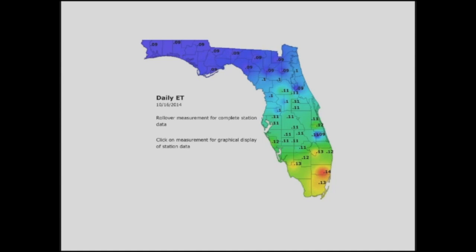All right? So that means they want to return the amount of evapotranspiration loss, right? But we know that that can change based on where you are in the state. It's very variable. In the state of Texas, you could be recommended to water a ½ inch a week up to 2 inches a week, depending on where you are, right? So it's very, very variable. In a perfect world, we'd all have a smart controller that calculated the ET for us, and we could set that we wanted to replace 60% of that loss every week. And that would be a perfect world, right?